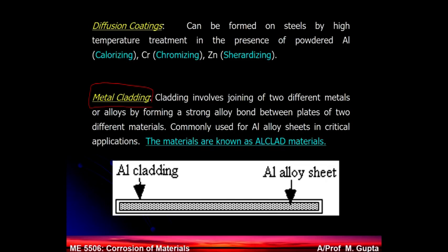You know that in the aerospace sector you have to use high strength alloys. So many times high strength aluminum based alloys are used. But high strength means more number of second phases. More number of second phases means more corrosion in the wet condition. So people say, single phase, how can I do that?